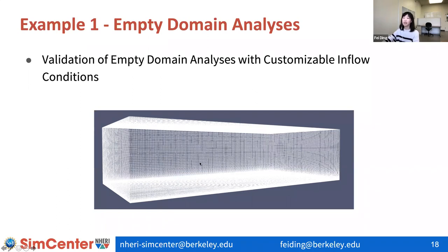It meets your targeted wind profiles, and then you can put the building model in your computational domain to run your CFD simulation. So today I will introduce how to customize your inflow conditions in the empty domain analysis using the wind tunnel data through the WEUQ application.